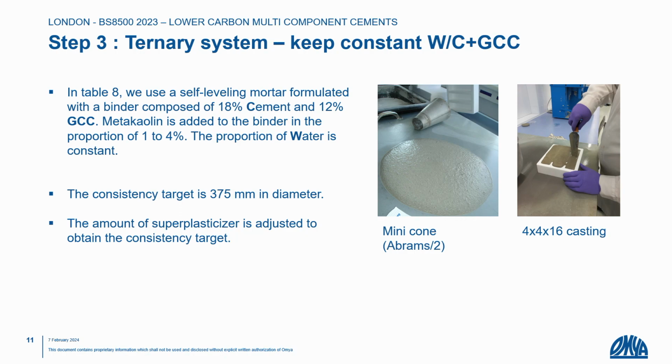This is the hypothesis. In this system, we decide to add the calcined clay, that is to say, we will increase the total powder content, but we want to keep the same flow behavior. And in this case, we will not add more water, we will add more superplasticizer.